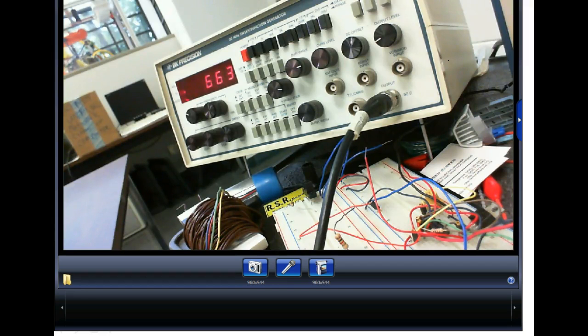So what we need to do is have the ability to demultiplex through filtering and stuff like that. What we do is we place the information on something called a carrier. And it's usually a frequency that's a lot higher than the information it's trying to carry. And then we transmit that over and we can have multiple frequencies on the same wire at the same time, which is pretty interesting. But then we have to come up and we have to get that off, right?